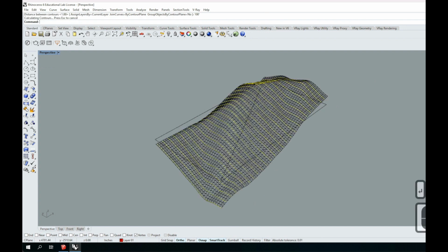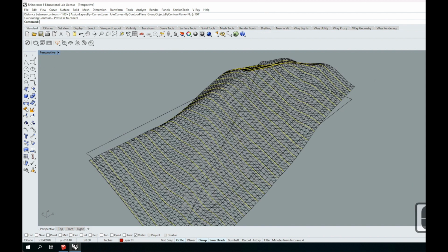Now, it turns out that the scale of this is such that I probably could do a more dense set. So if I'm looking at this, this happens about every 3 triangulations. So I could really do it about every 33 feet and get better results. So I'm going to press Ctrl-Z to undo. And then I'll do that contour one more time.